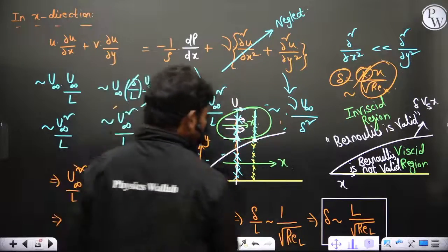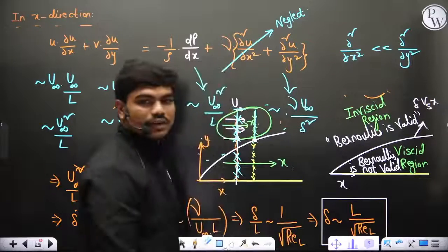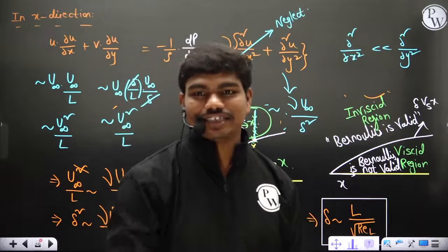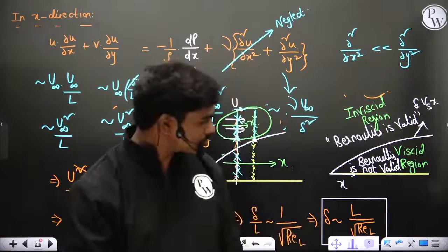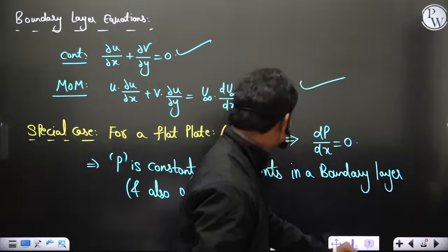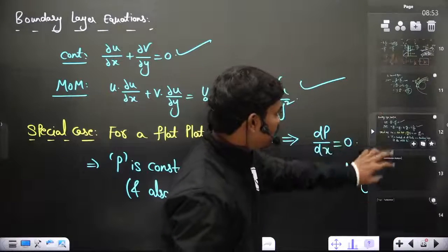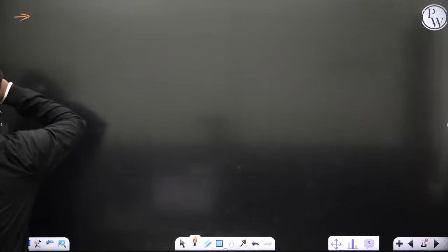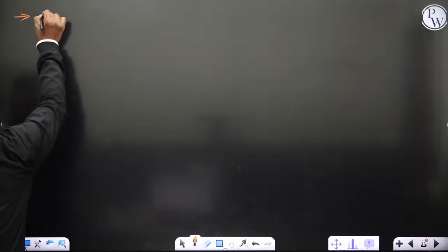Fine. So now let's talk about the boring and common stuff, which is displacement thickness, momentum thickness, energy thickness, all these things, which you generally know. Do you all know the expressions directly? Then yeah, here. Let's see certain important parameters which are important in understanding drag forces. Why do we calculate this kinematic thickness, dynamic thickness, all these things? Practically this is for calculating drag forces.